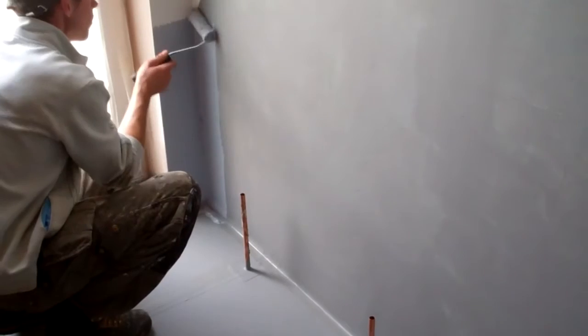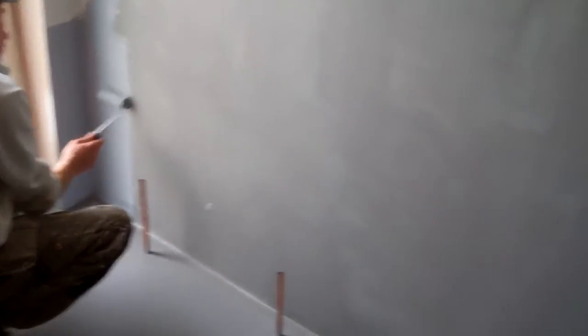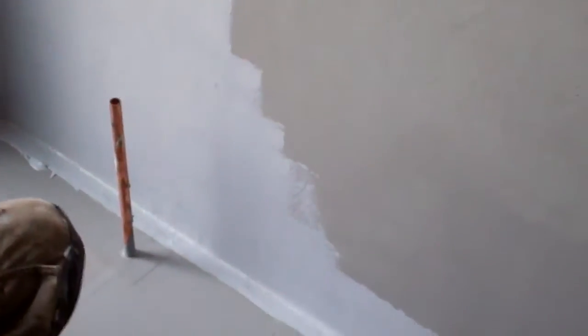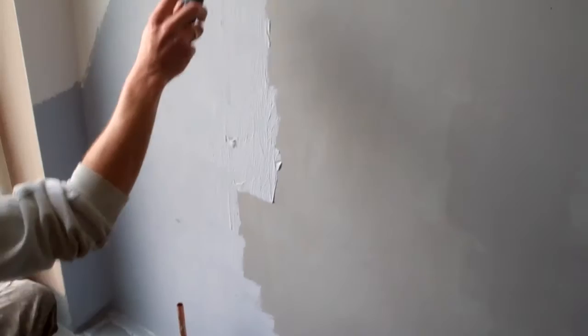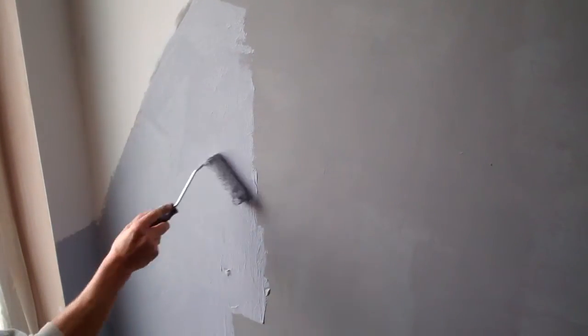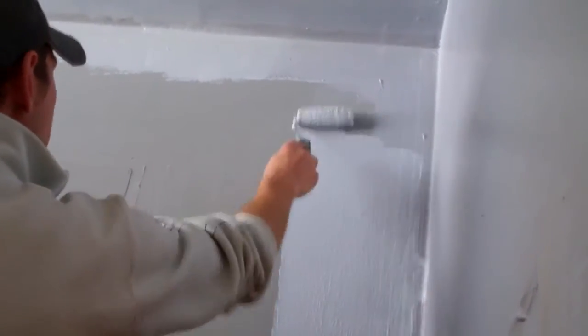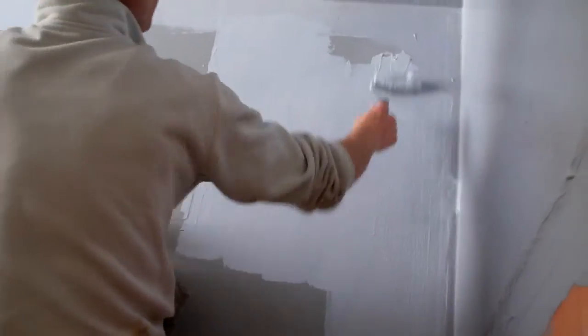The aquaproof is applied over the entire wet room floor with a turn-up of at least 100 mm onto the walls. In the immediate shower area, the walls are completely tanked. As the distance from the shower head increases, the tanking can be brought down at an angle until it reaches 100 mm from the floor. In this way, all areas of the wall subject to running water or significant splash water are fully protected.